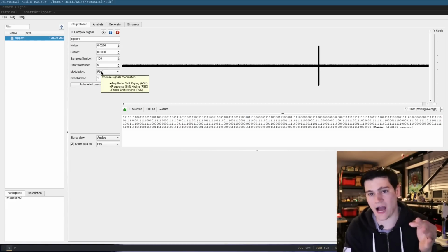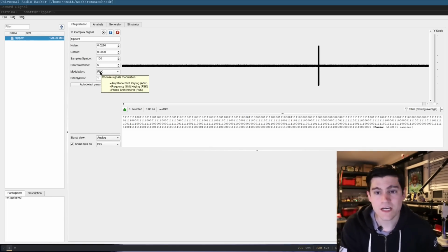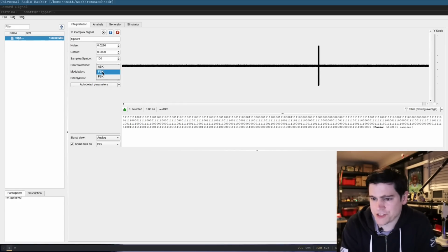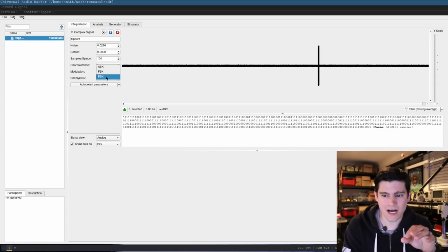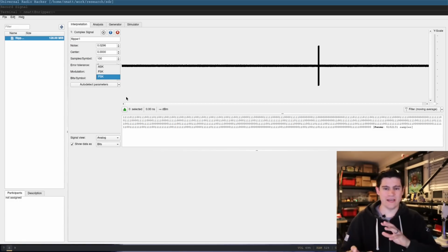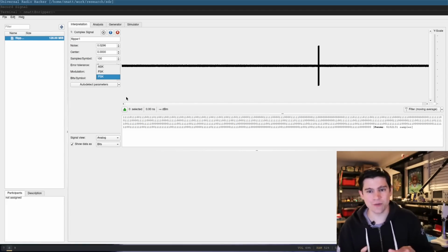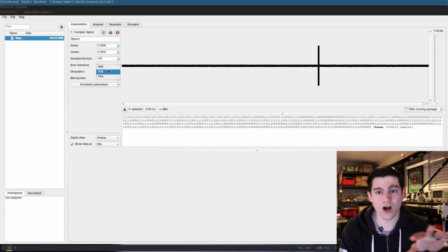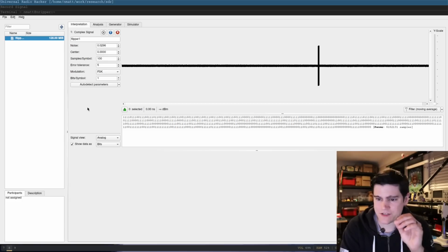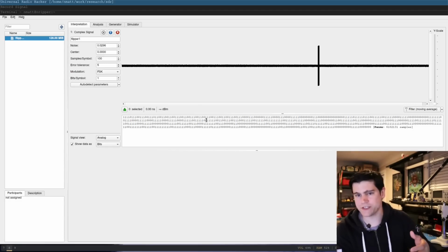That's my hypothesis, which obviously I already know because I've prepared for this video a little bit. So this is going to be our modulation instead of something like ASK. Again, I'm learning in the radio realm, and determining if something is PSK is a little more fuzzy to me, but there are ways you can determine that. So we're going to set the modulation type to FSK when we start to decode the signal.